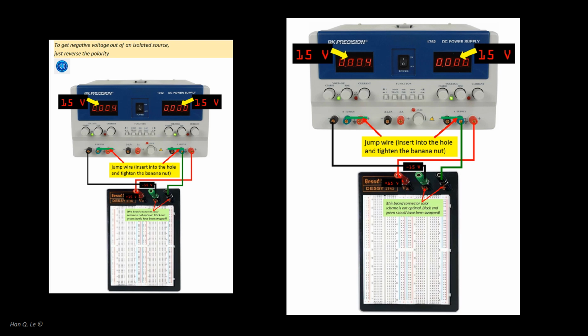The most common cause of burnt op amps is erroneous power connection to the board. Indistinguishable, or inconsistent color coding of the wires is an accident waiting to happen, and invariably so. Consistent color coding scheme like this case can help reduce this risk.